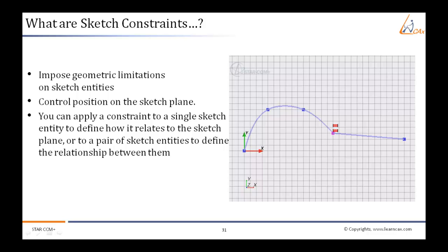Constraint offers an indirect advantage. In the process in which we create a sketch, we do not have to think about fixing or taking decisions on the size and position of a sketch. When creating sketches, we can just go on creating them and then put constraints one by one, bringing them to final form.